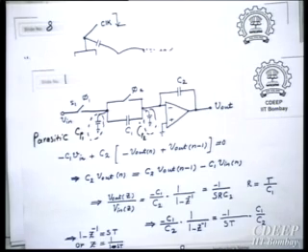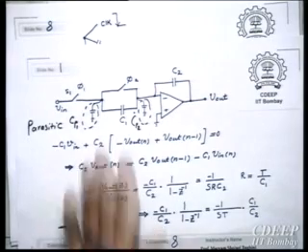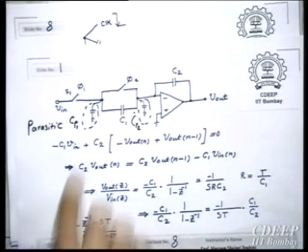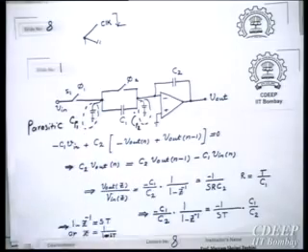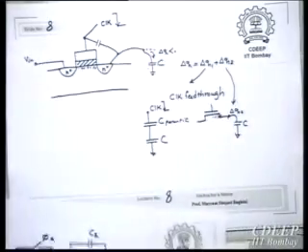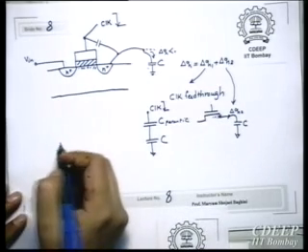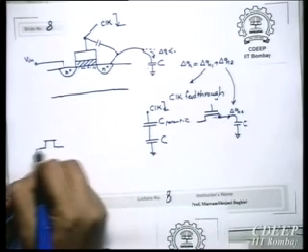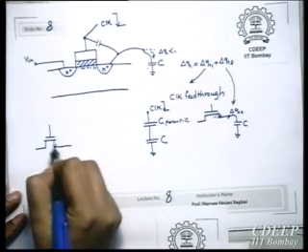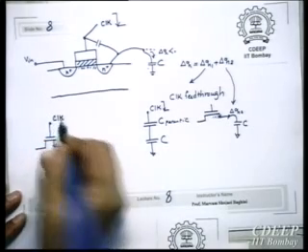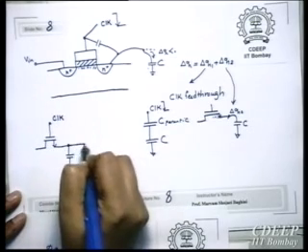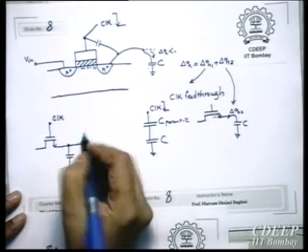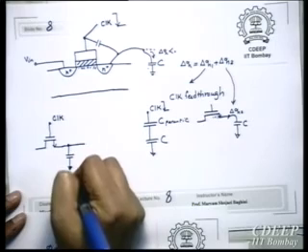So it's always better not to use capacitances in this fashion. We have to create a path to ground which allows this additional charge to go to ground, or use some tricks for switches. For example, for clock feedthrough, you may have seen, if you have this switch and you have a clock here and you have a capacitor here, or it might be connected somewhere else, not necessarily to ground, wherever it is connected.